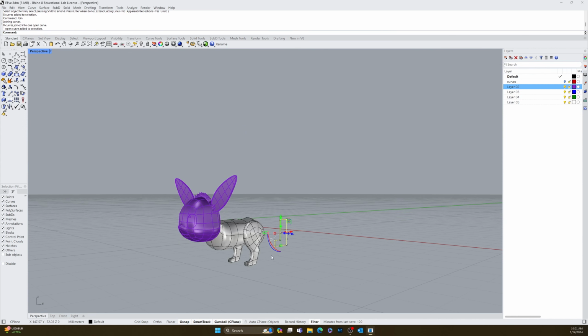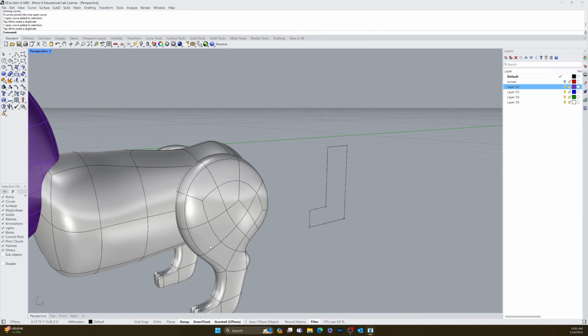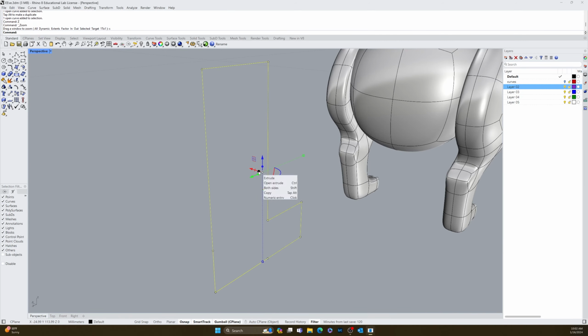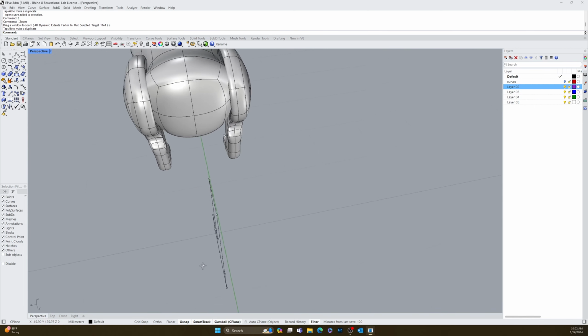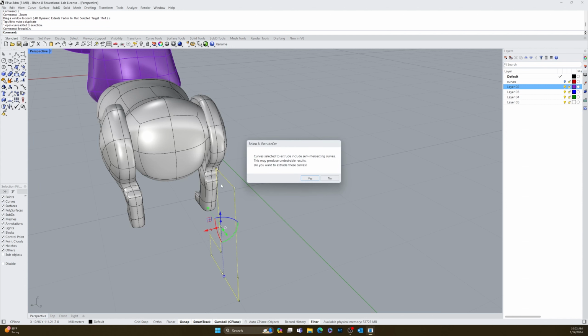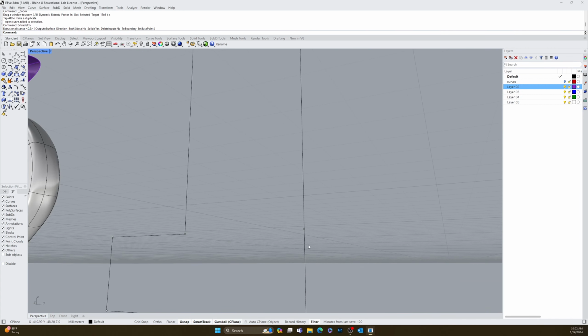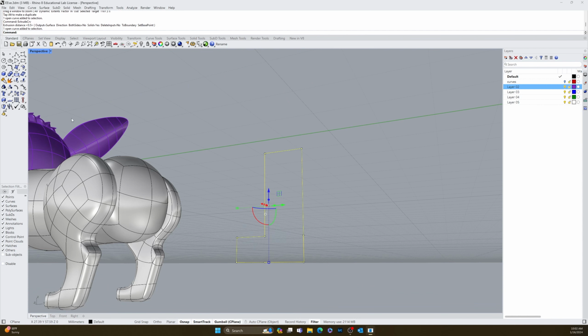And perspective, extrude, oops. The curves do not extrude and intersecting. Okay, I've got some stealth intersecting thing going on here. I don't know how I did that. Oh, I know. Let me explode it. So that's a good thing to notice. I have overlapping curves. So these curves down here, delete that one.